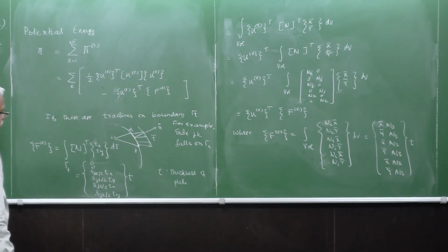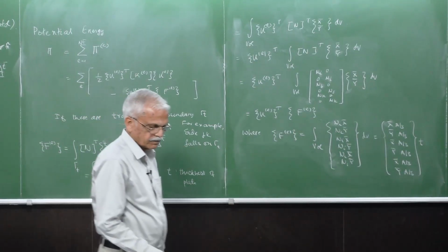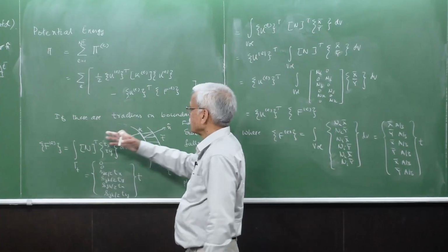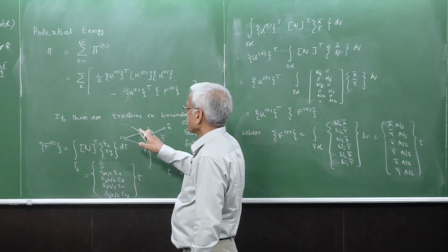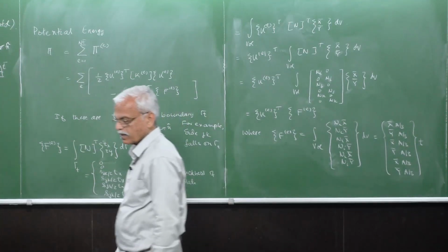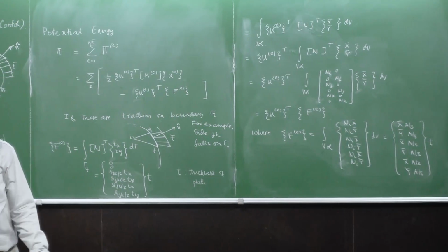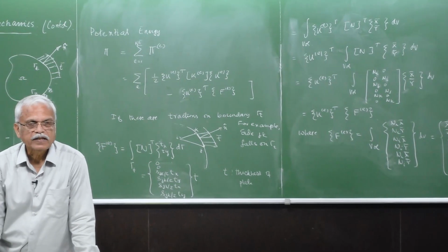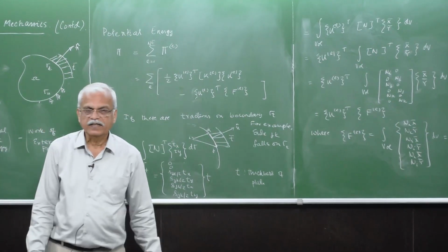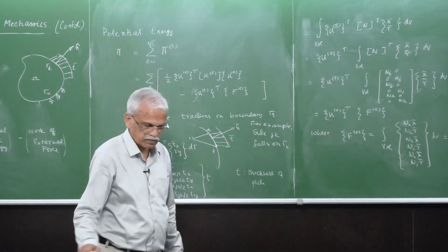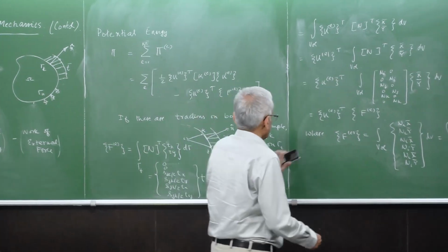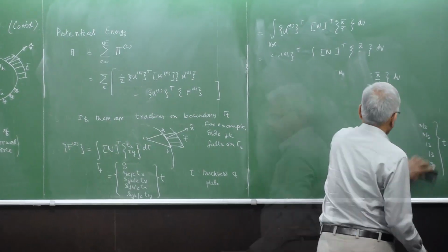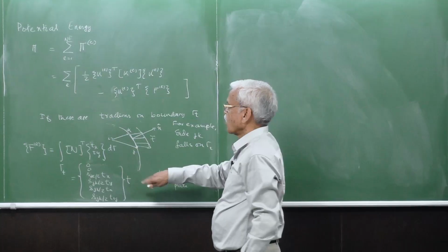okay. So these are all the forces, and we may also include a concentrated force, say at some other node, say at K. If you have a concentrated force there, that also needs to be included, that concentrated force multiplied by the nodal displacement at that point because it's acting at the node. Okay, so those things can be taken care of. So now let's summarize everything here. So this may include this also, right?